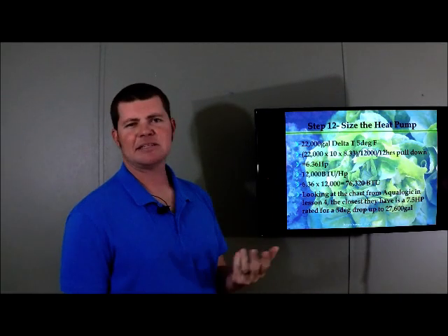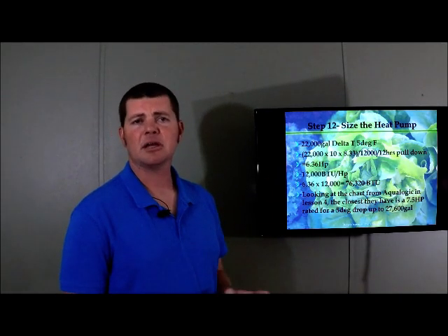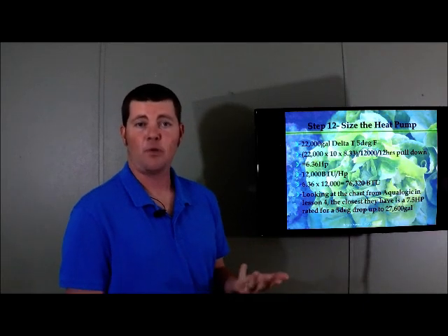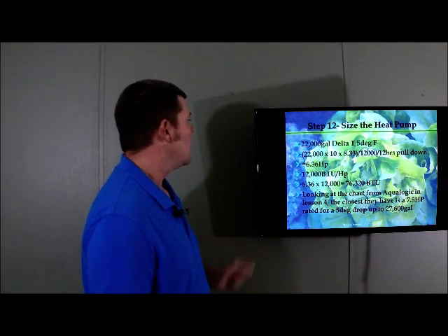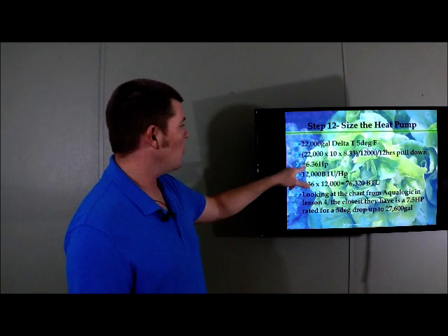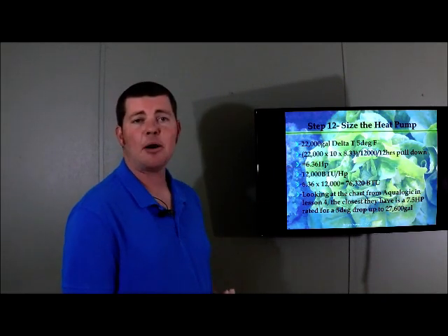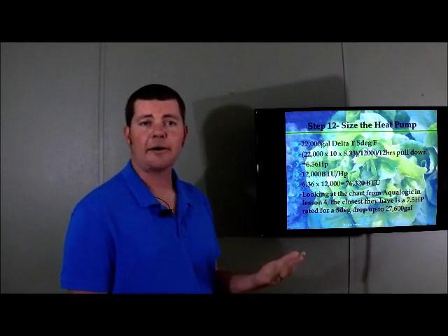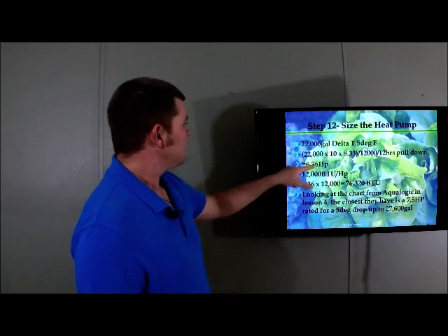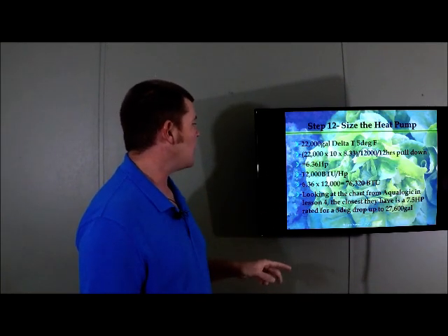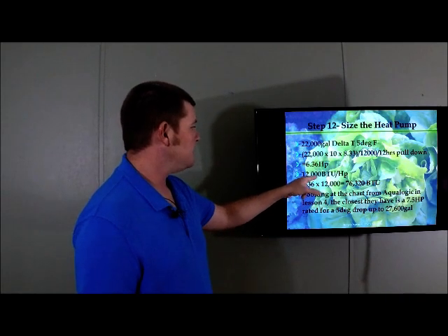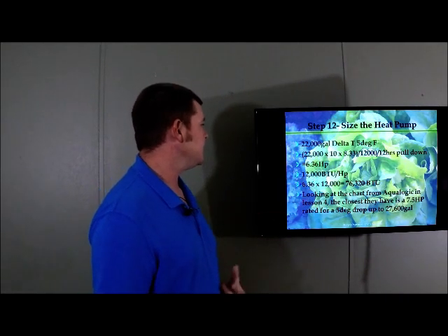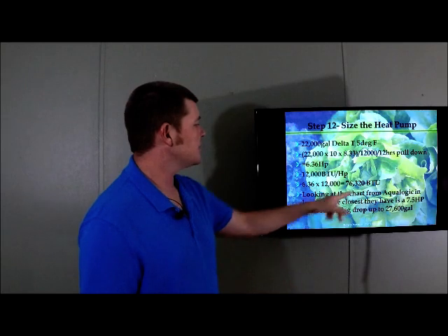And I believe that's in week 4 where we did equipment sizing. I gave you the formula for sizing chillers. Okay, this gives us 6.36 horsepower needed for the heat pump. And again, a heat pump will chill or heat the water. So it does both. 6.36 horsepower. If you want to look at it in BTUs, it's 12,000 BTU per horsepower, which gives us